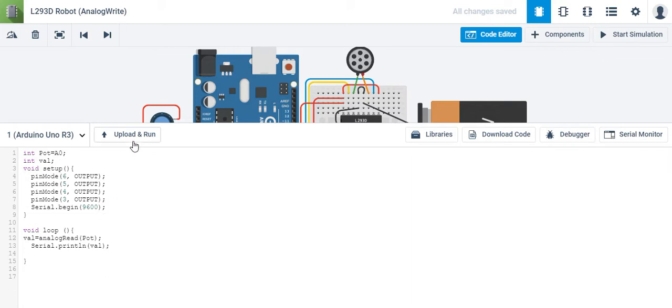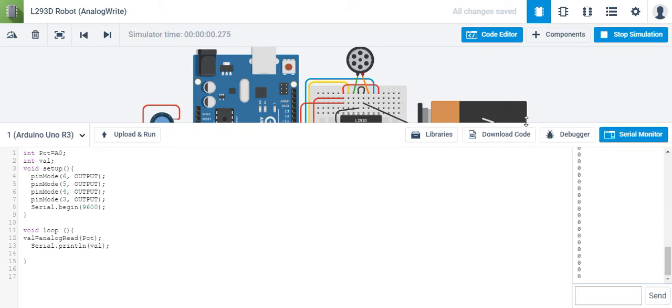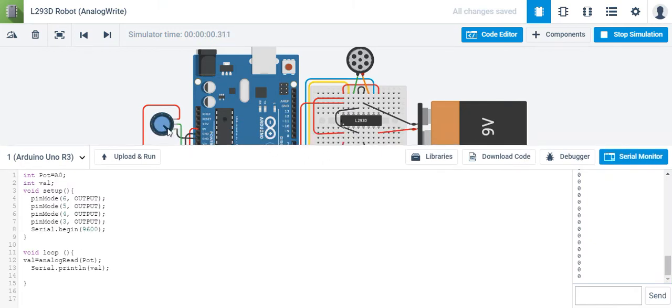And if I run this, I'll click on my serial monitor and you'll see a whole bunch of zeros, and hopefully if I move this potentiometer, you'll see those values change. So 246 is where it's currently at, and if I rotate my potentiometer, you'll see my values increase. If I rotate my potentiometer all the way to its max value, it'd be 1023. So your potentiometer ranges from 0 to 1023. We're going to utilize that data and manipulate it to move our DC motor here.